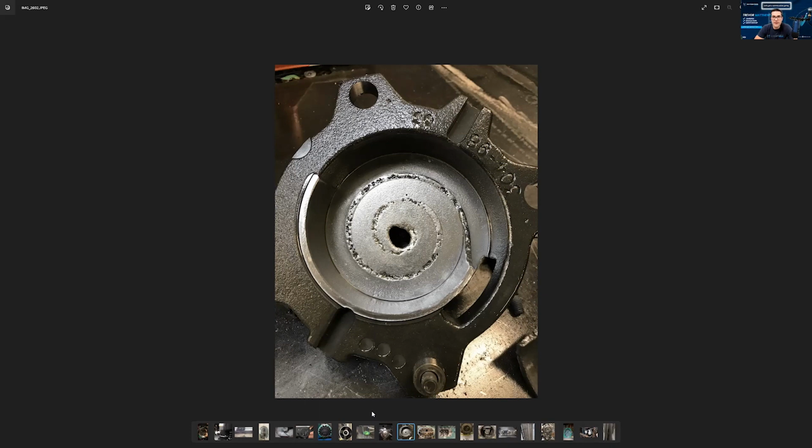It's easier to find in those semi-hermetics because you pull it apart. And once again, you can't just say, oh, it was liquid, because not necessarily was it liquid refrigerant. It could be oil that caused the slug. Especially in the scroll, yeah, definitely could be liquid, because you have that massive explosion. You've got liquid refrigerant underneath the oil, and that oil flies up in there and does the damage. So these are some of the things that you want to look for.